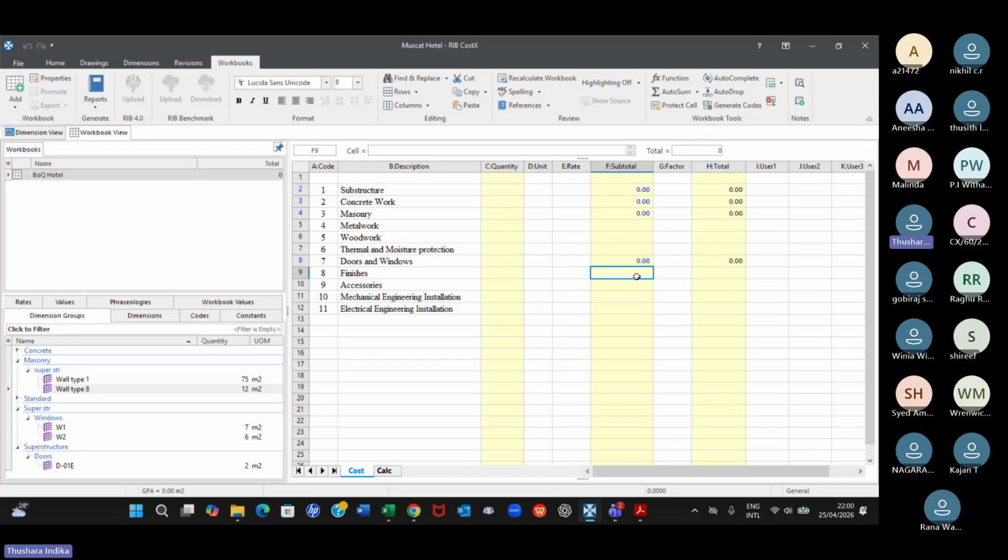You have to just follow the same way that you have followed for others, like for example, area measurements. Now you know how to get the area measurements, right? When we measured the PCC, you did the area measurements. So similarly, finishes also, it's a matter of creating a dimension group for each finish type.